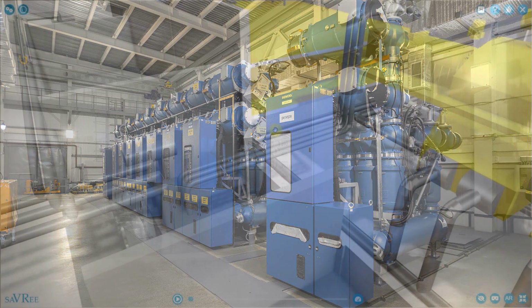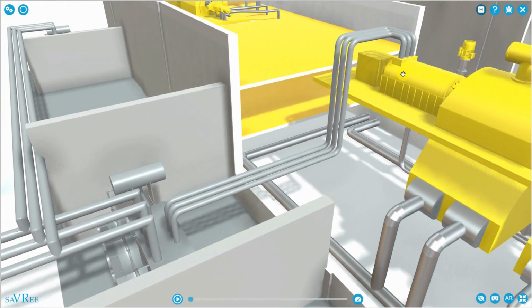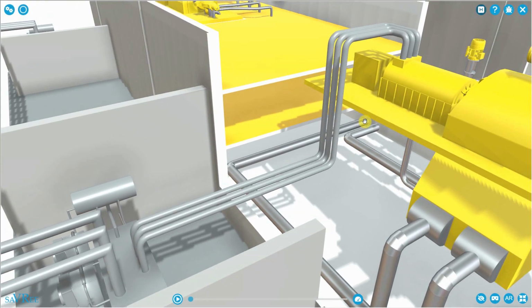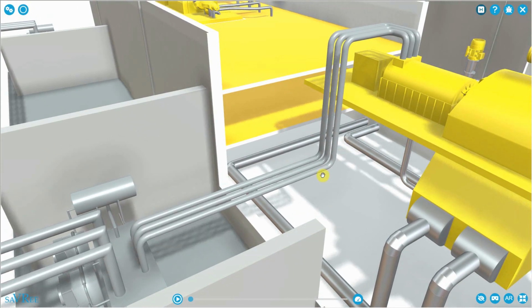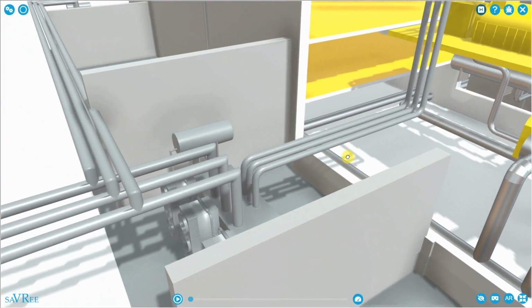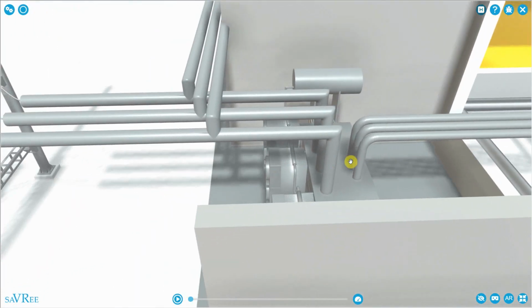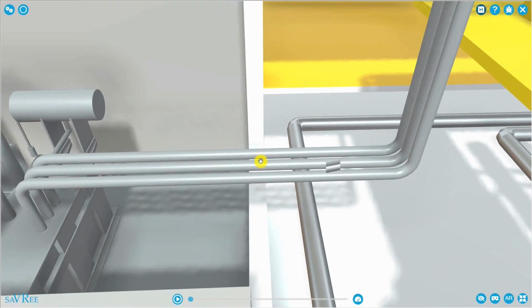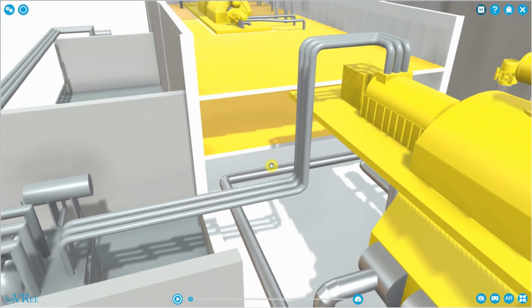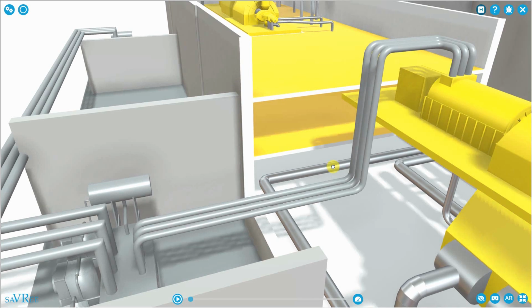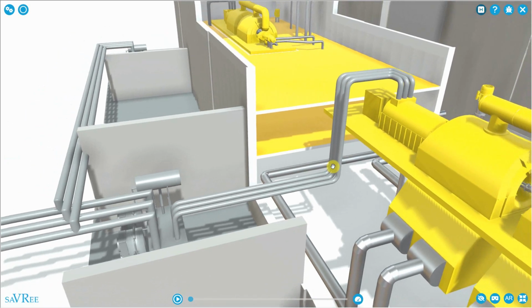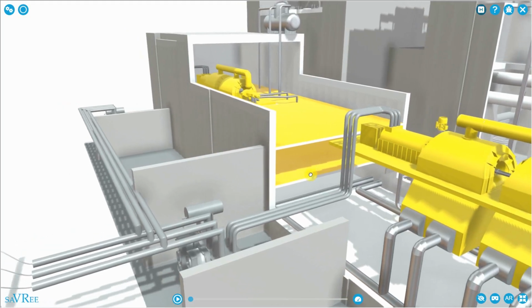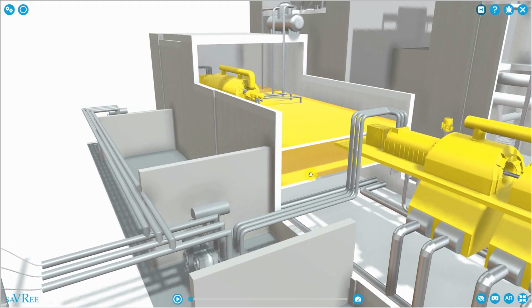For example, if we had a generator fault, then we would want the switchgear installed between the transformer and the generator to automatically open and protect our electrical transformer. If the electrical transformer has a fault, then we want our switchgear, which is installed between the transformer and generator, to open and protect our generator. So you will see switchgear installed between all major electrical components because that's the only way you can protect the components from each other should they have an electrical fault.